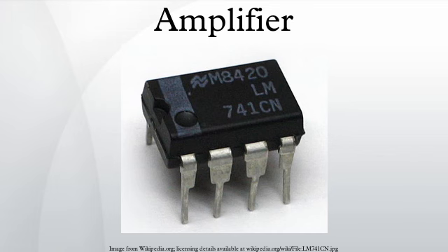Traveling wave tube amplifiers are used for high-power amplification at low microwave frequencies. They typically can amplify across a broad spectrum of frequencies. However, they are usually not as tunable as klystrons. Klystrons. Klystrons are specialized linear beam vacuum devices, designed to provide high power, widely tunable amplification of millimeter and sub-millimeter waves. Klystrons are designed for large-scale operations, and despite having a narrower bandwidth than TWTAs, they have the advantage of coherently amplifying a reference signal so its output may be precisely controlled in amplitude, frequency and phase.